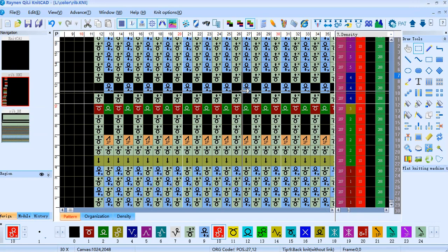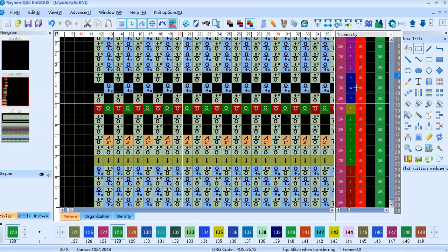We always make the transfer density one number, but it is not fixed. I told you, in our training center, number 10 is the transferring color. You can change it to 21 or 22, anyone, because we totally have 128 colors. We can make transfer use two numbers, two colors. You can choose any from 1 to 128.